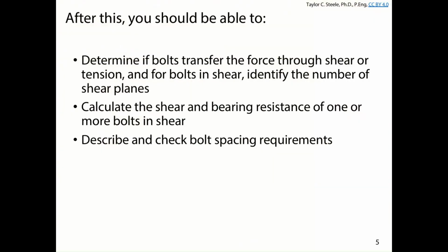Basically, after today, you should be able to determine if the bolts are carrying the force through shear or through tension. And for bolts directly in shear, identify the number of shear planes. So single and double shear should come to mind, and I have a polar wear activity to help us think of that before we get into things today. You should be able to calculate the shear and bearing resistance of one bolt in shear. We're going to focus on bolts in shear.